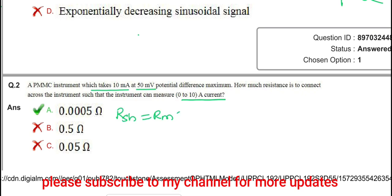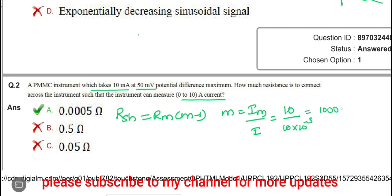RS is equal to Rm into M minus 1. What is M? M is the maximum value of current divided by meter current. The maximum value of current is 10, divided by meter current, which is 10 milliamperes, so 10 into 10 power minus 3. The 10 gets cancelled, so it is going to be 1000. Next, what we need to find is Rm, the meter resistance. Rm is equal to Vm by Im, meter current. The meter voltage is 50 into 10 power minus 3, divided by current 10 into 10 power minus 3. These two get cancelled, so the meter resistance is 5 ohms.